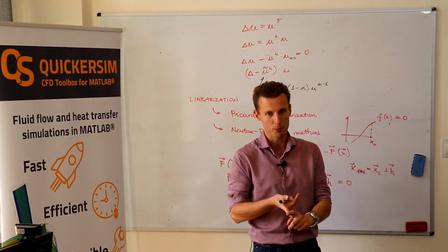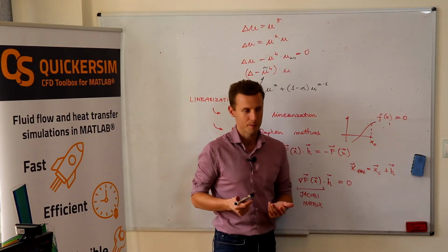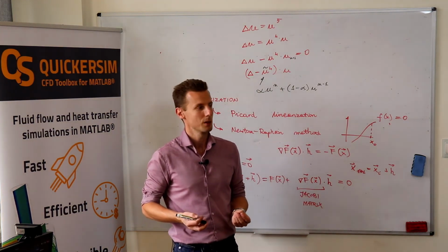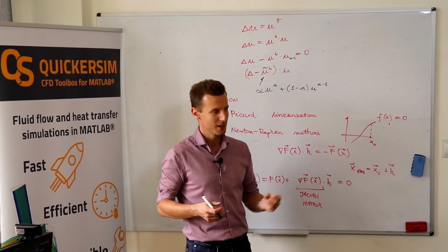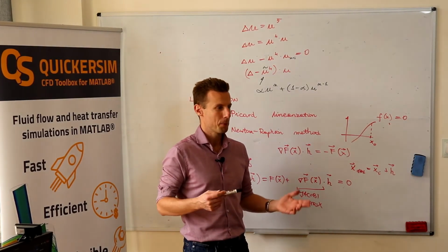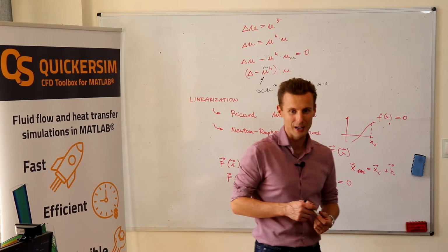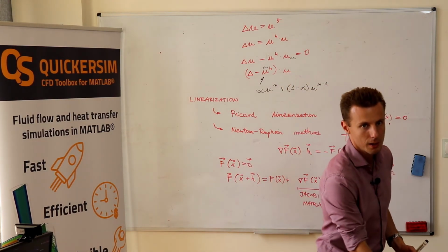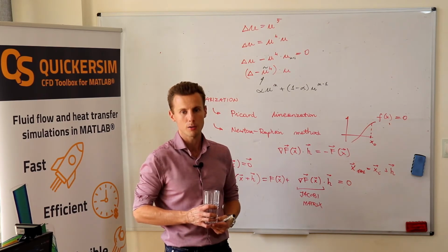There is no other option if you have no heat sources or something like that. Unfortunately, in the numerical schemes, you may get oscillations and wiggles, and then overshoots or undershoots, like 22 degrees. Not very nice, absolutely not physical. Maybe it does not always cause problems, but in some cases it may.